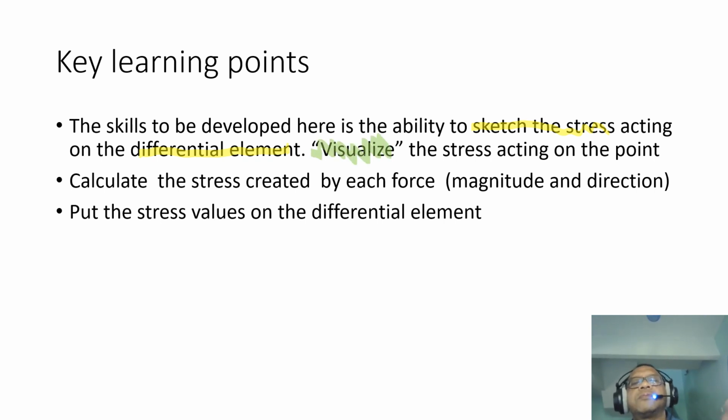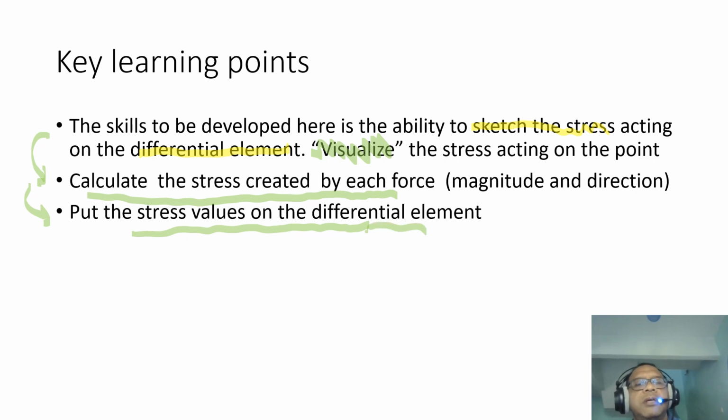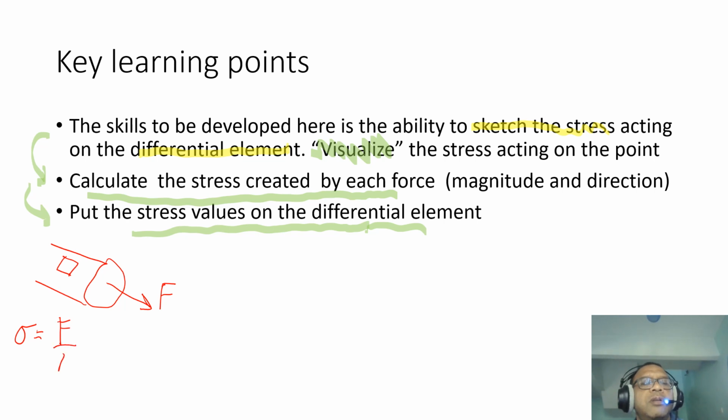In order to do that, you have to calculate the stress created by each force, and then you put the stress values on the differential element. I'll repeat it here. For example, this is your axial load, and you want to find the stress acting on the differential element, so you know what that is, and you now know that it is tensile. So this is what you do.